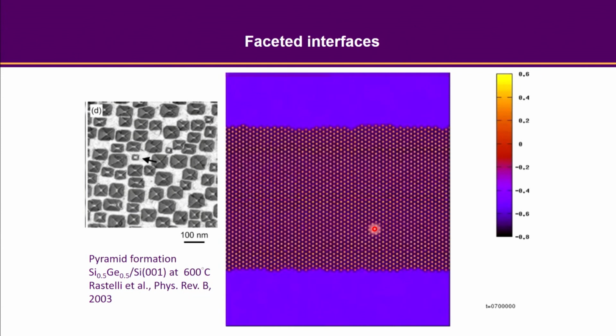But for a different setup, for example if the temperature is different, you can also have pyramid formation, which means if you look at the detail of the island, you are getting something like facets. So in a PFC, you can crank up the parameter epsilon, because in the multi-scale analysis, we show that a smaller epsilon gives you a diffusive interface, but a larger value of epsilon gives a rather sharp interface. So here, I am going to still compress the solid, but crank up the epsilon to a certain larger value. And I am also adding noise. So here is the result of the simulation.